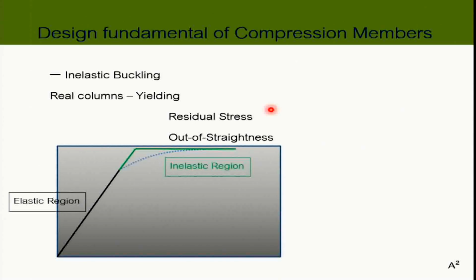And that restraint from the web and so on will cause the section to have stress before we even use it. That is why it is called the residual stress. The stress that is already there before we put the load on our structure. So the stress does not begin from zero. Okay? That is one thing that we need to put onto Euler's curve.